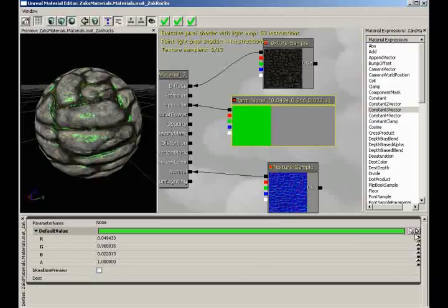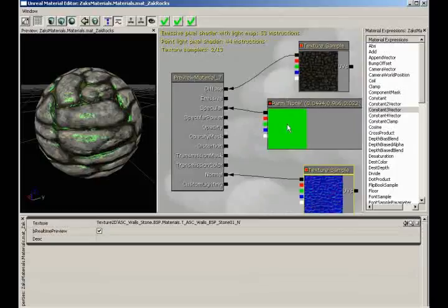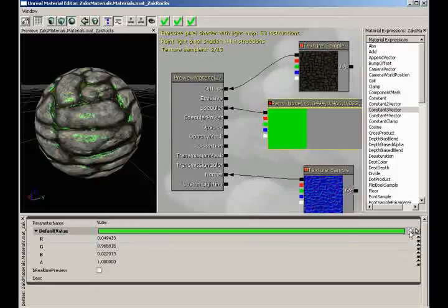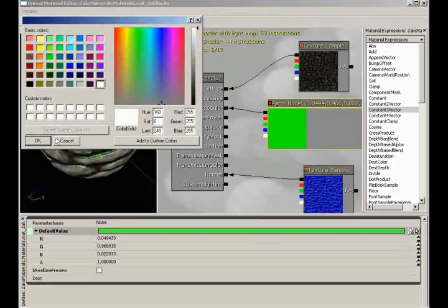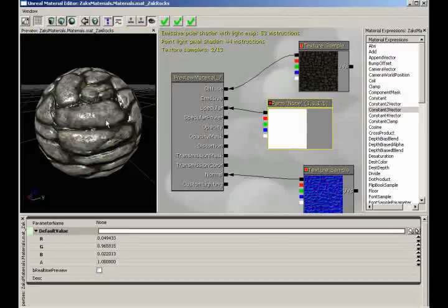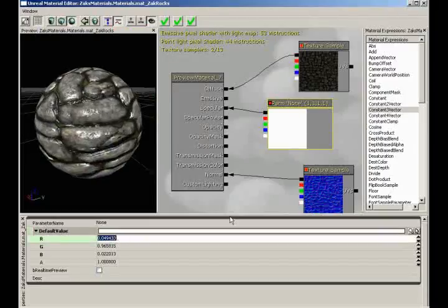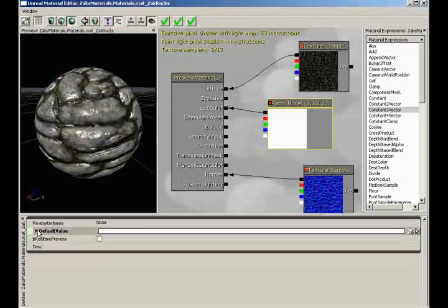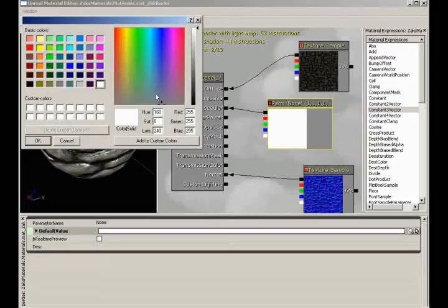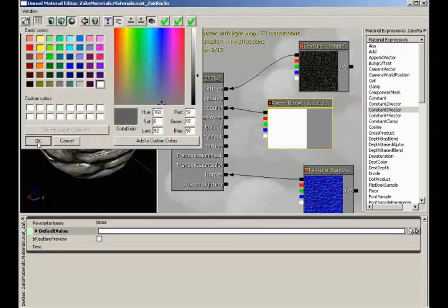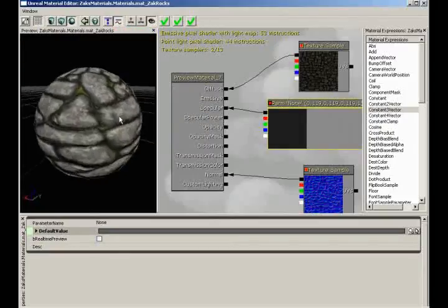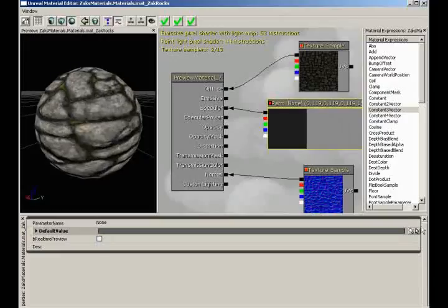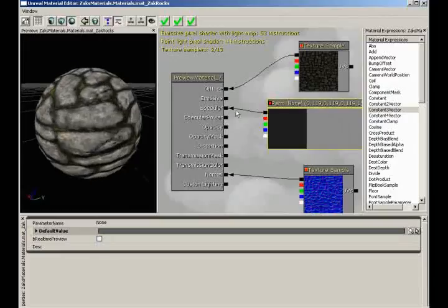All I'm just showing you is that our specular channel controls our amount of specularity, and it controls the color. I've shown you the color, but let me set this over to white for just a second. And you'll see everything goes back to white. If I start setting this to darker values, which in the end essentially just boils down to shades of gray, so I can pull this down to 50% gray, we are in effect reducing the amount of specularity we have. In fact, it looks like we've kind of nullified it, but if we hold down Alt and switch off specular,